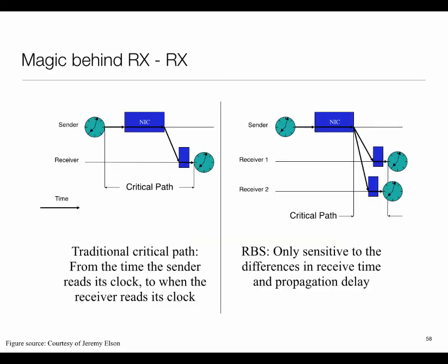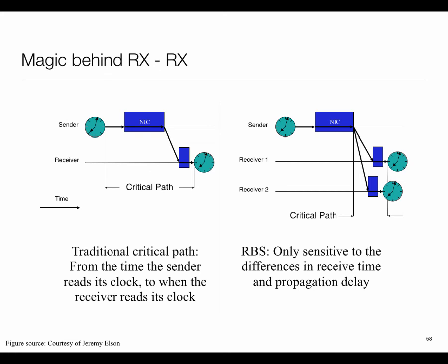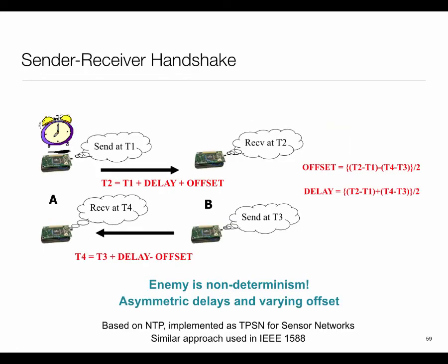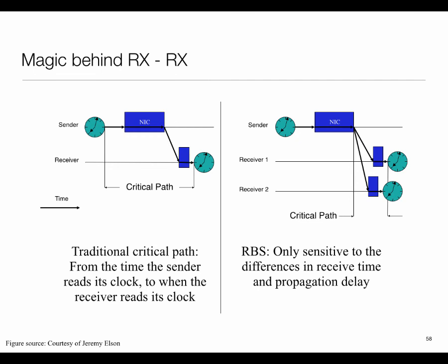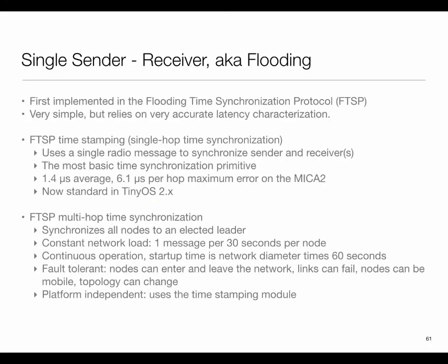And it has a peculiar consequence. In situations like underwater networks, where you are doing acoustic transmissions, that divide by 2 helps a lot, whereas these schemes face the full brunt of the error. So you would see that in many situations, particularly underwater, these bidirectional schemes do much better than these unidirectional schemes. The message I'm trying to give is that which one is better depends upon a lot of circumstances: your technology for timestamping, the precise situation you are in, bidirectional versus unidirectional, and the type of signaling that you are doing.